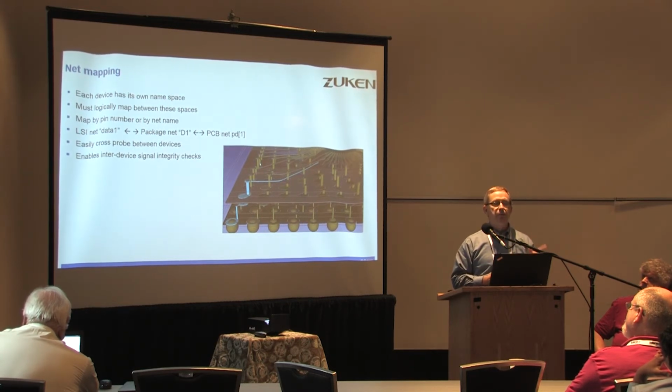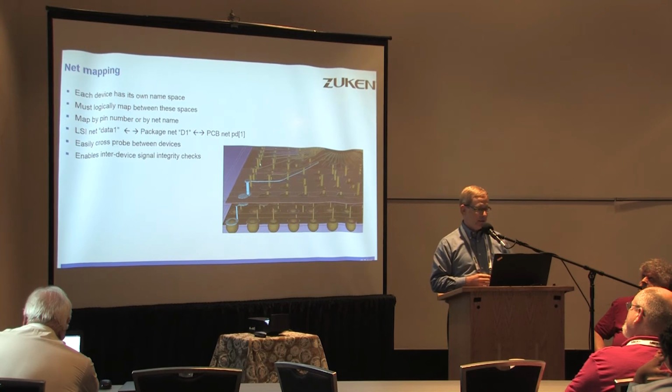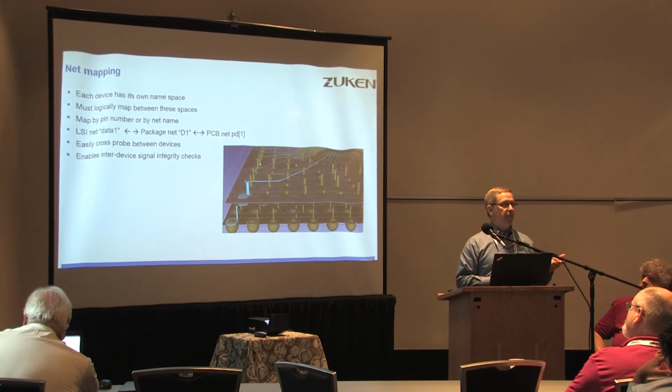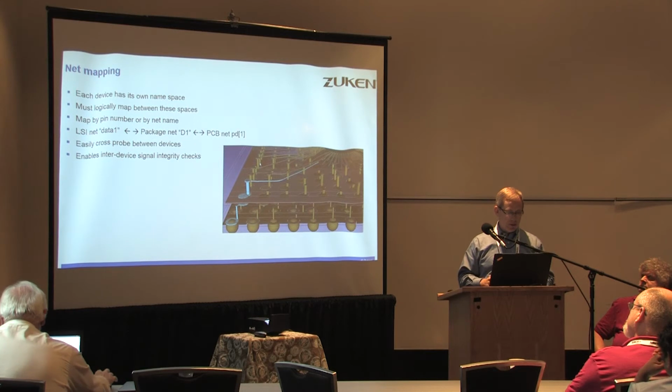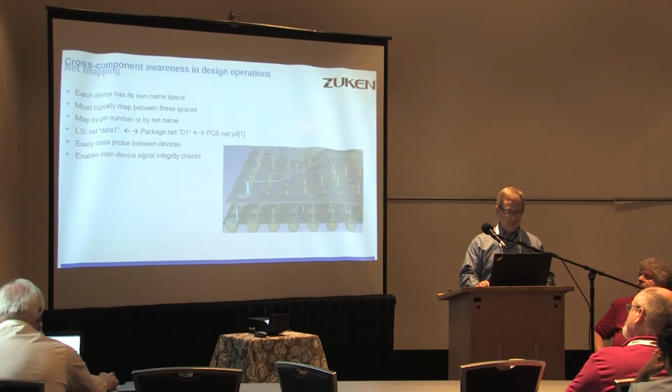You have to logically map between these spaces. The LSI net might be data 1, the package net might be D1, the PCB net might be PD(1). Those all map together. You need a tool that does that mapping between those spaces, and Design Force does. So when you're working and popping between them, you can always know which net you're talking about and be able to cross probe and analyze accordingly.